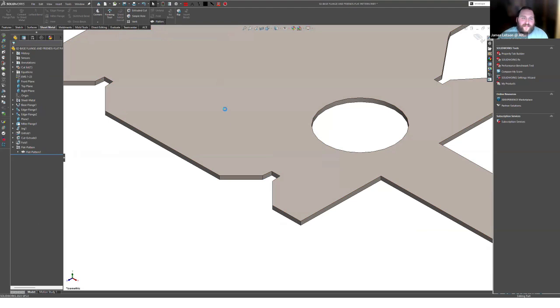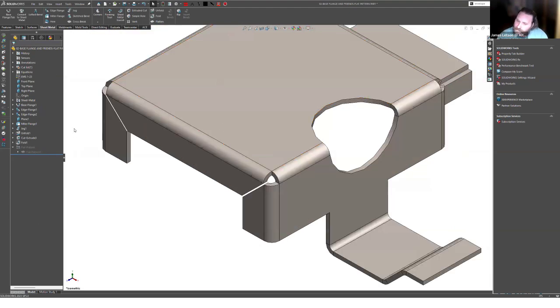So I think that the corner treatment button is really just for those companies that have very specific corner treatments that they want. Like they like to add an extra amount of clearance for their press brakes or something like that. So that would be where you would check that corner treatment box, right? You don't want it to apply this, you want to apply your corner treatment yourself.